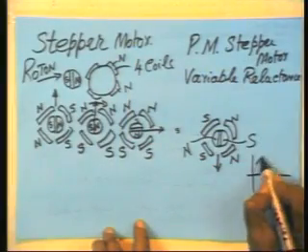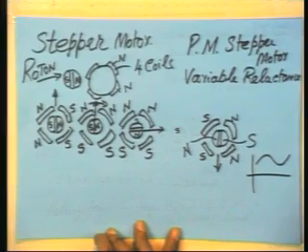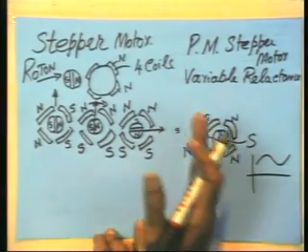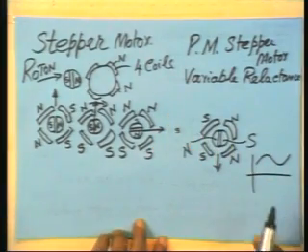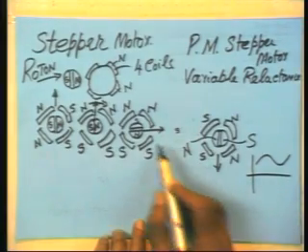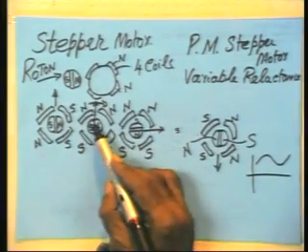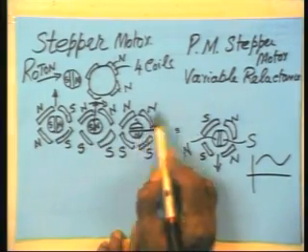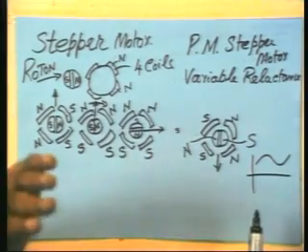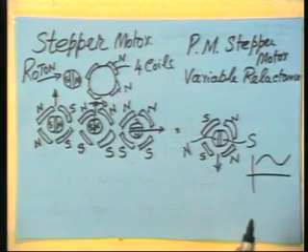Now the torque output of the rotor is going to fluctuate as it moves between these magnets. So you will get a torque varying like this. And the minimum push or minimum torque is obtained when it is in between two positions. See, it is starting here, it is ending here, somewhere in the 45 degrees in between, you get the minimum torque. That is the running torque.